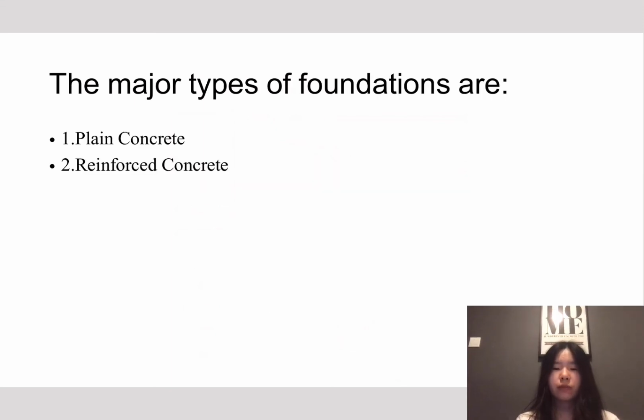The major types of foundation are plain concrete and reinforced concrete. Plain concrete is non-reinforced concrete pad foundation, and it's an economic choice under relatively light loads. Reinforced concrete allows relatively wide but shallow foundations, often designed with a square plan area, and has a higher carrying capacity than plain concrete pad foundation.